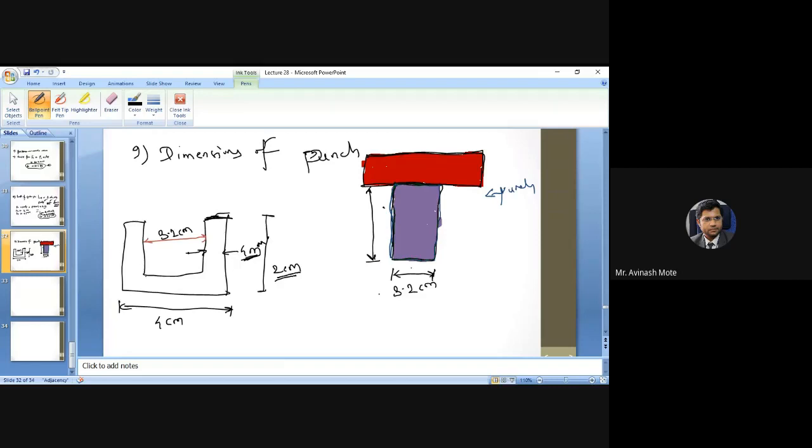But now if you check this lower base part, the punch is not going to pierce here. It is not going to pass through this solid part. The movement of the punch will start from this position. It will compress the material and reach this part only at this level. This bottom part is a solid base. So this movement will be from this top point to this one.